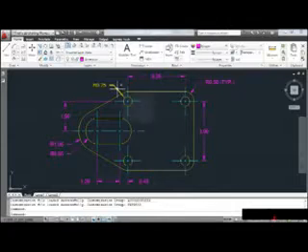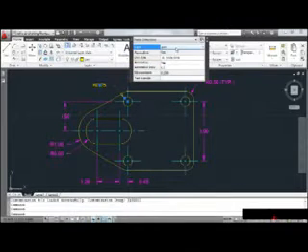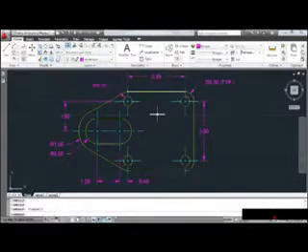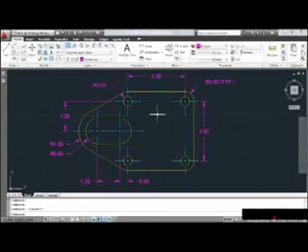Finally, I'll use my setting to put this radial dimension on the correct layer. Using the Quick Properties tool, we can change our settings much faster because the tool is just inches from our cursor. And as an added bonus, we can customize the tool and load it up with the settings that we use most.